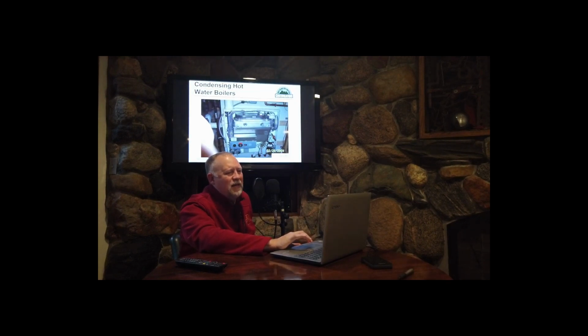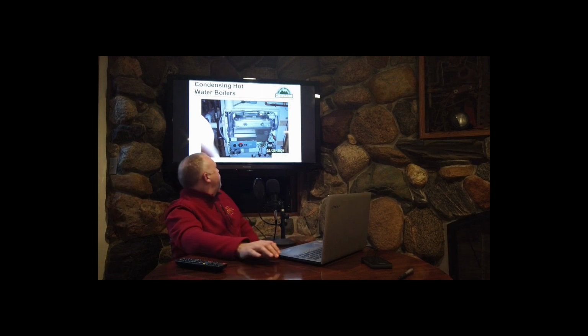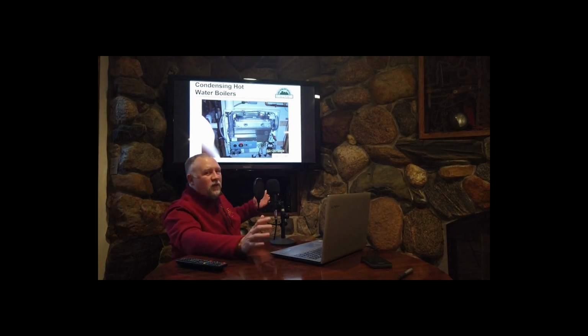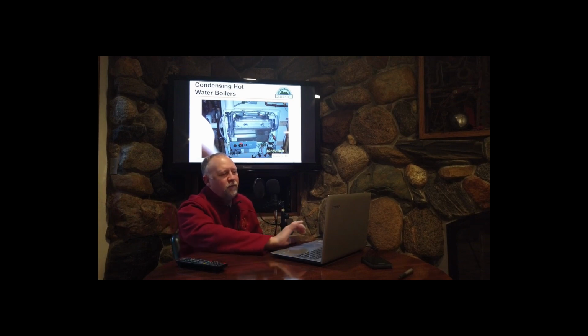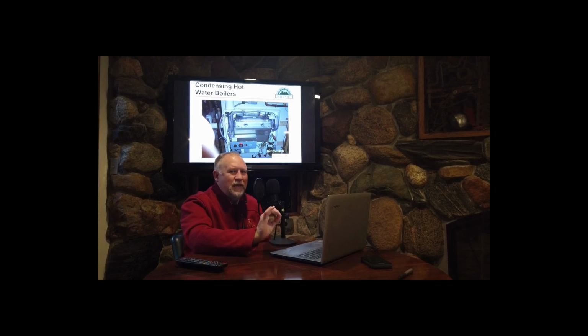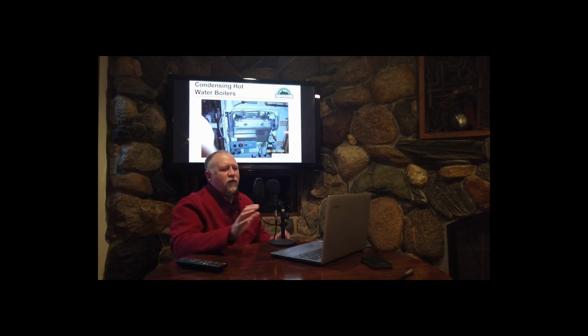All right, a condensing hot water boiler. So we're still making hot water. It's just that water coming back from the house has to be much cooler. To get more heat transfer from the fire to the water, we have to have that water as cool as possible.